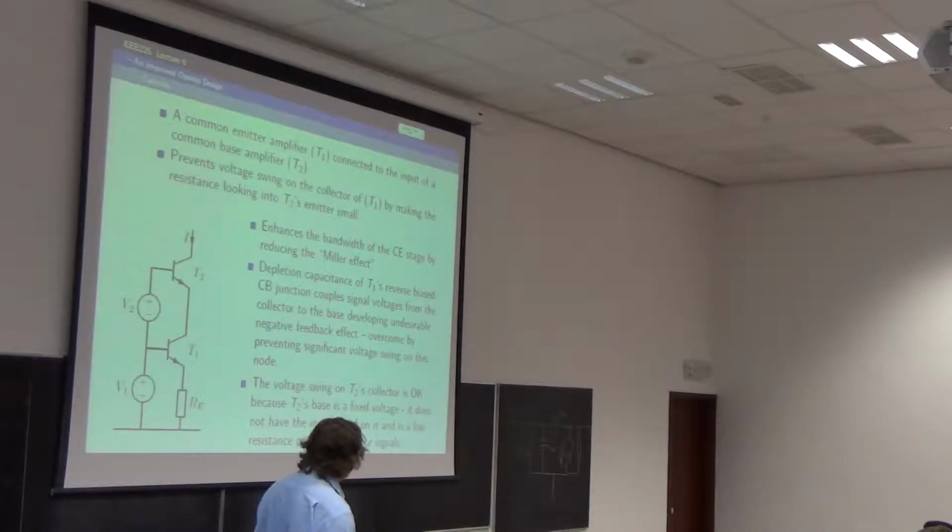Just as we had a mechanism of feedback with this RE by putting a resistor in here and summing up the currents on this node, we had a current contribution from the collector and a current contribution from the base, both putting a voltage across RE, and as a result, the base emitter voltage was affected by a portion of the collector current flowing in RE because it produced a voltage across it. And that we said was a kind of feedback. Similar arguments apply to collector current flowing through CBC and adjusting IB, which flows in DC.